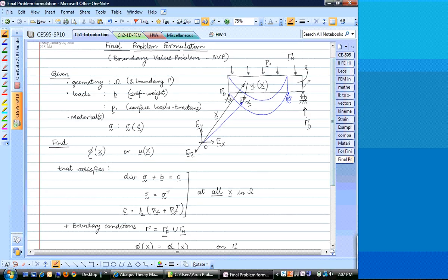This is just a collection of points on the boundary. What we are saying is that on part of the boundary you have to specify some displacement, and if you don't specify some displacement, what happens? So you have this beam. Let's say you apply a moment, it goes to a deformed position. If you take the beam some other place, apply the same moment, you still get the same solution, but with a rigid body translation plus rotation. So that solution would not be unique unless you give me some points where the displacement of the boundary is specified. Okay.